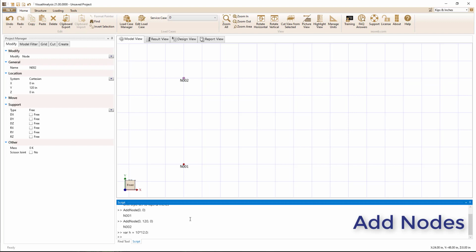We can also define variables and perform math in the command line. Note, when storing a value in a variable, the line must end with a semicolon. Variables circumvent the need to input the same number over and over again. A semicolon can also be used at the end of the command to suppress the return value. For convenience, the up and down arrow keys on the keyboard can be used to auto-populate the command line with lines that were previously entered.